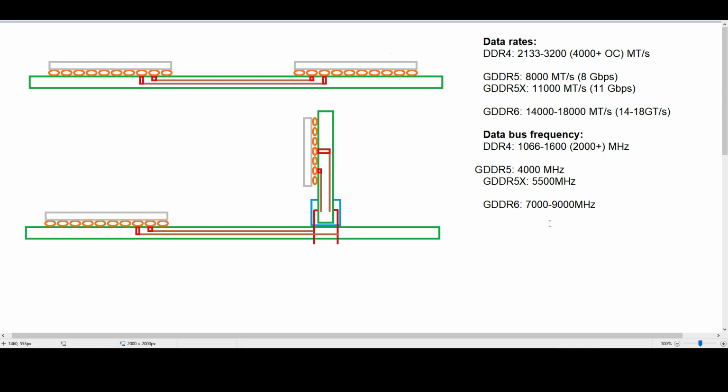So the objective, of course, is to minimize that noise, and one of the key ways to minimize that noise is making the signal path, so all of our conductors that take the signal from our sender to the receiver, as simple as possible, and have them be as uniform as possible, so the least possible change in the diameter, the cross section, the shape, and the material.